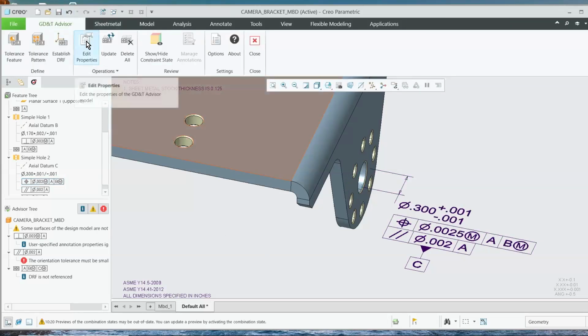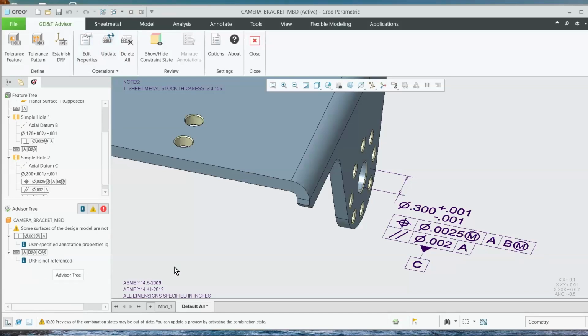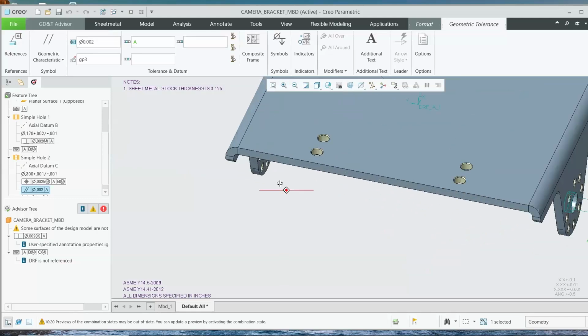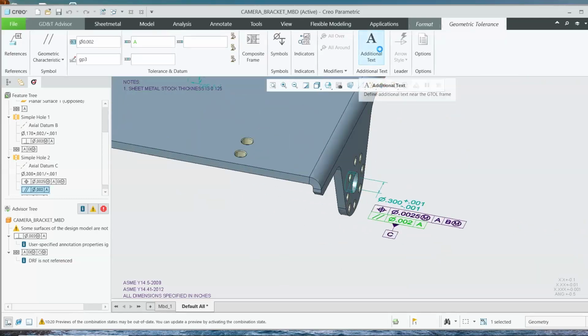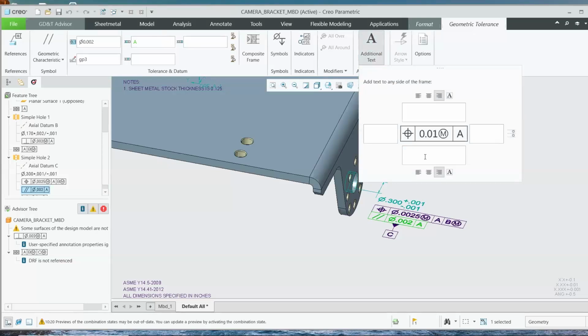And now when we update things, the error message goes away. And in this particular case, we could also come in here. Since there's a hole on this side and there's the exact same thing over there, I'm just going to come in like I did before, and we could just say this one is in 2 places.